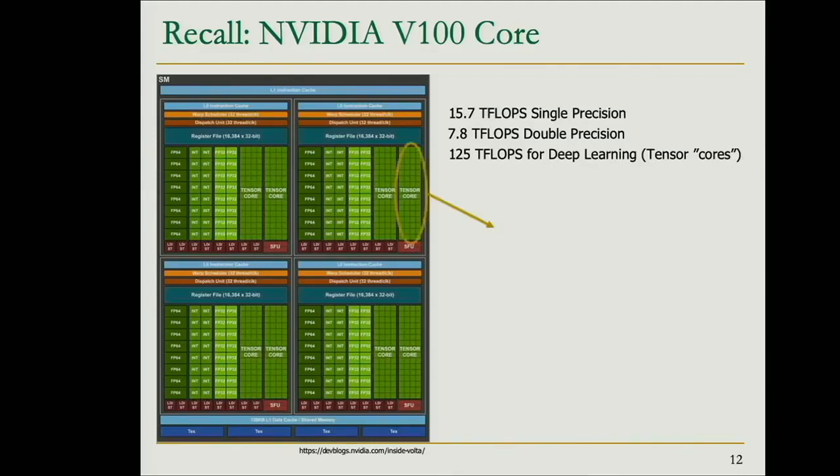What exactly do these tensor cores mean? Well, it's something like this. For each of these tensor cores, we are going to be able to do this kind of computation. Observe that we have 2 input values, we multiply them, and then we accumulate the partial result with more products coming from other tensor cores. As you can see, this is able to do a sort of mixed precision. We are not working with single precision or double precision floating point operands, but with half precision.